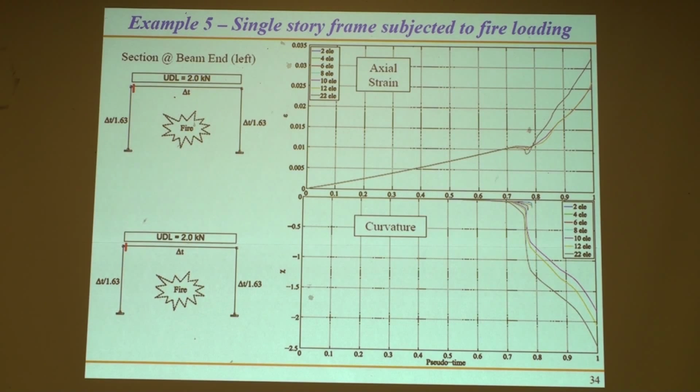With temperature, it's a little bit tricky because, in concrete, the plastic hinge also grows as you're doing your analysis, right? Initially you don't have a plastic hinge, and then it starts developing and grows. In steel, with the fire, and we saw there, we have the axial effects, and the plastic hinge also changes length as you increase your temperature. So you have to come up with a reasonable value for your plastic hinge, and then work with that.